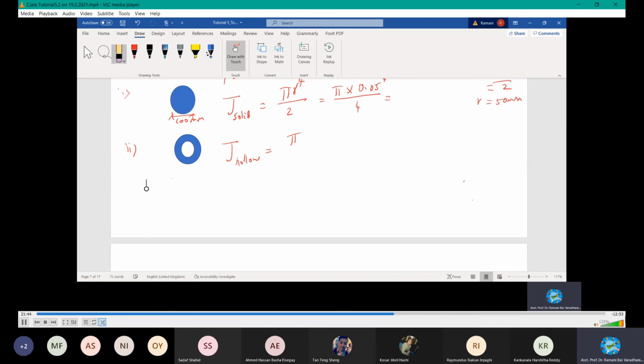We need the radius, right? What is the net radius? The radius will be the subtraction of the net radius. We only need this portion, and we don't need this portion. The stress is distributed over this size of the member, because it is hollow here. There is no stress distribution where the material is not there. The material is there for this section only. Just now we found that this is 12.5.